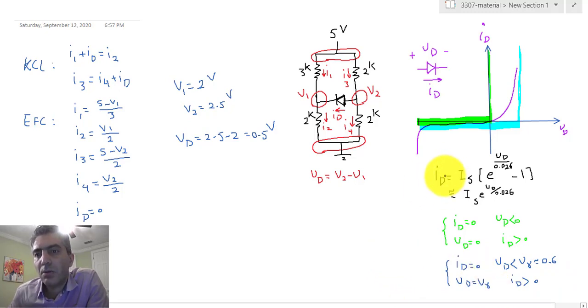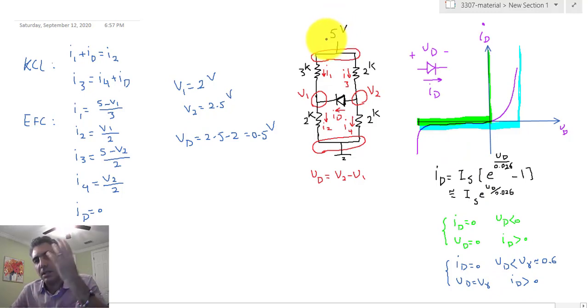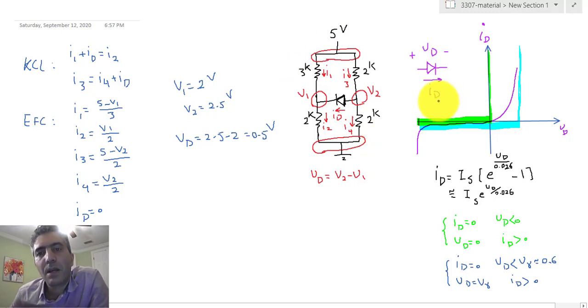How do you know later on? Well, if you're just on your own, if the voltages that exist in the circuit are comparable to V gamma of a diode, then you better consider V gamma and use the second approximation. If the voltages are large, like this voltage right here was really large, or you're dealing with hundreds of volts, sometimes just ignoring V gamma is not going to make a big difference, and you're fine if you make the oversimplified and ideal approximation for the diode.